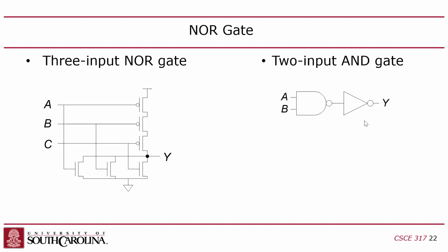Likewise, in order to have a 1 output, you've got to have at least one 0 input, right? So that disqualifies an AND gate from being created, for instance, because when you have an AND gate, your inputs are 1, 1, and the output is 1, right? But that won't work because if your inputs are 1, 1, there's no way to pull the output up to 1, right? So you can't build an AND gate.